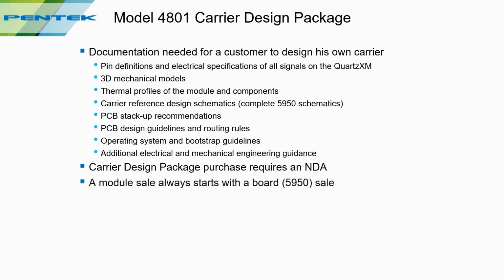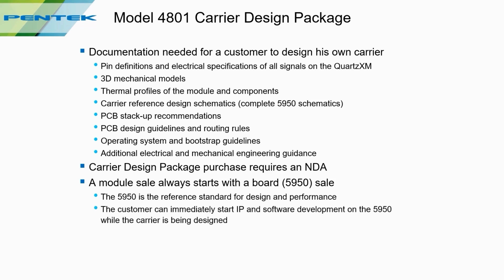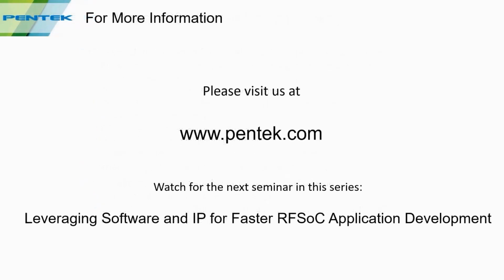And we say that all carrier design sales start with a board sale. And the reason for that is very simple. When you're designing your carrier, most customers that have been doing this at the same time are developing all their IP and their software on our 3U VPX product. So when the carrier design and the PCB is finished, they can move that Quartz XM module onto their carrier, and at that point they have all the software and the IP created, and it's a matter of just moving it over and testing it. Also, the VPX card can be a reference to go back and check performance or use it as a debugging environment. So that was my last slide.